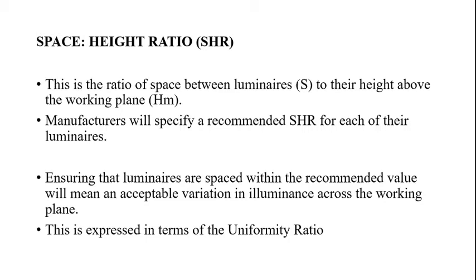The luminaire you purchase from the market will have a manufacturer's data sheet, and in that data sheet they will specify everything: the desirable room index, the desirable mounting height, the desirable maintenance factor value, and the desirable reflectance value. All that will be given in the manufacturer's data.